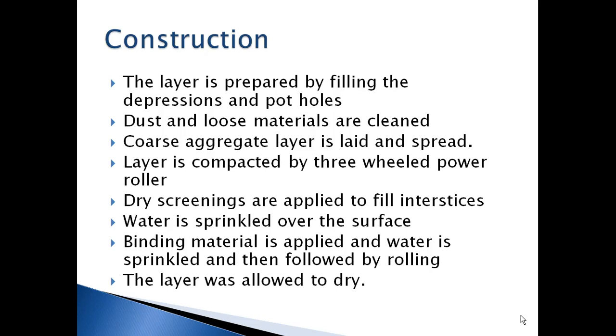Then the dry screenings are applied to fill the interstices or the spaces. Water is sprinkled over the surface. Binding material is applied and water is sprinkled and then followed by rolling. The layer is then allowed to dry. So these are the procedures how the non-bituminous layers are laid.